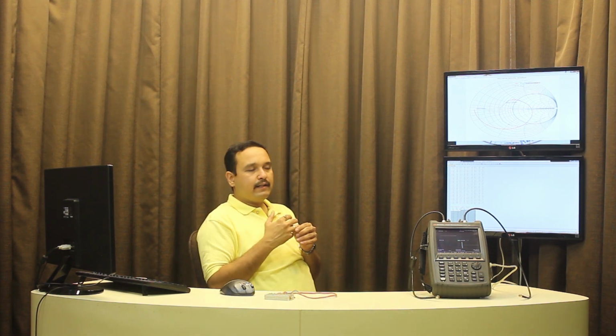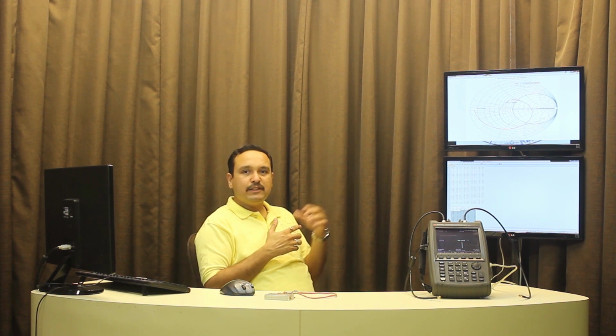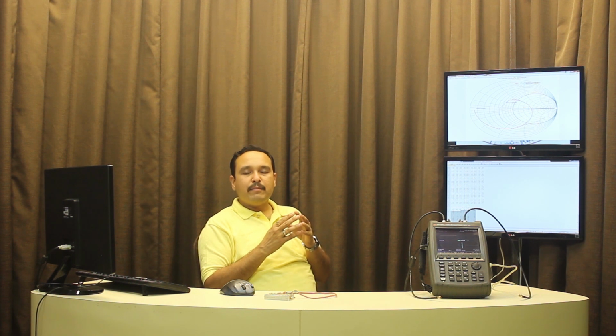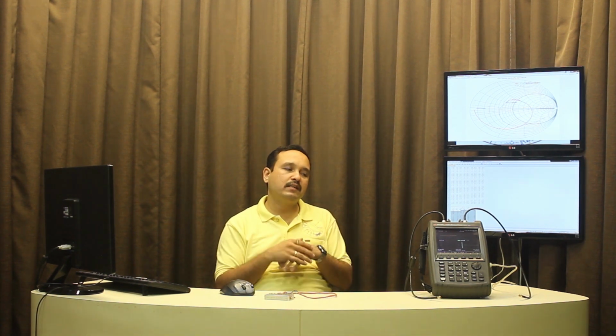But before going there, if you could recall from the earlier Smith chart data, the manufacturer has given us the transistor data between 800 megahertz and 10 gigahertz, while we want to do a design say between 500-600 megahertz to 1.5 gigahertz, 1.6 gigahertz.